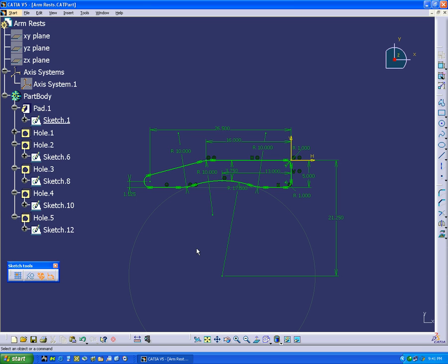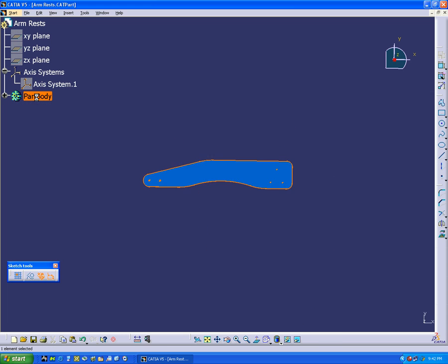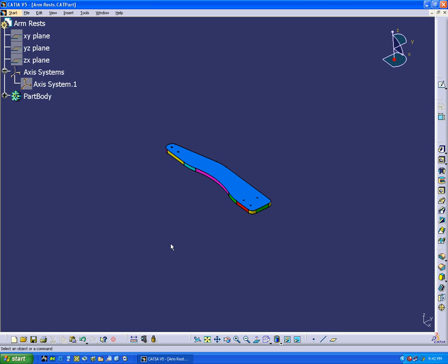So anyway, we come in here and we sketch on a sketch plane, and we create these line elements and these points, and then we constrain them with dimensions and radiuses, and we define geometry to drive in a pad. Basically extrude that geometry. So I can double click on the part file here and go back to the actual armrest.